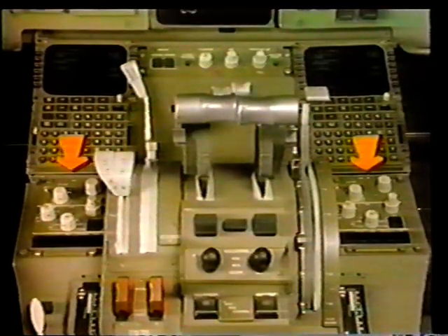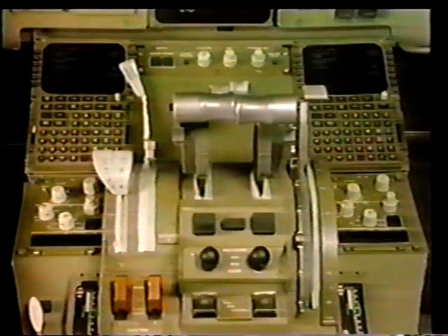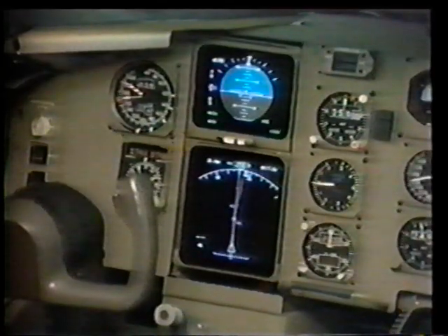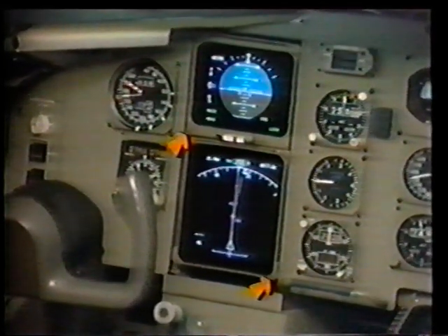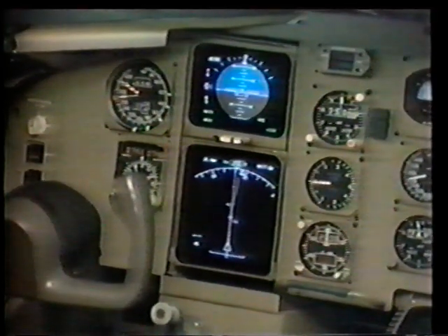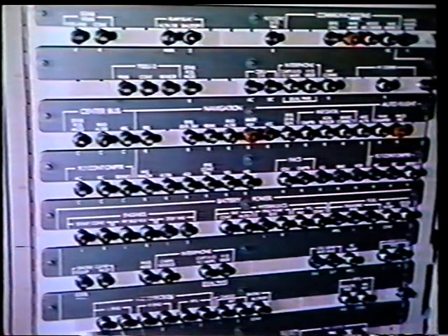Information from the symbol generators is managed by separate control panels on the forward control pedestal for each pilot's instruments. The upper panel controls the EADI, while the lower panel controls the EHSI. EADI and EHSI display brightness is adjusted manually using the brightness controls. After the brightness is set to the desired level, 2 remote light sensors located on the P7 glare shield panel and local light sensors mounted on the EADI and EHSI maintain the selected intensity throughout varying light conditions, including direct sunlight. Power for each EFIS component is controlled by individual circuit breakers on the P11 overhead panel.